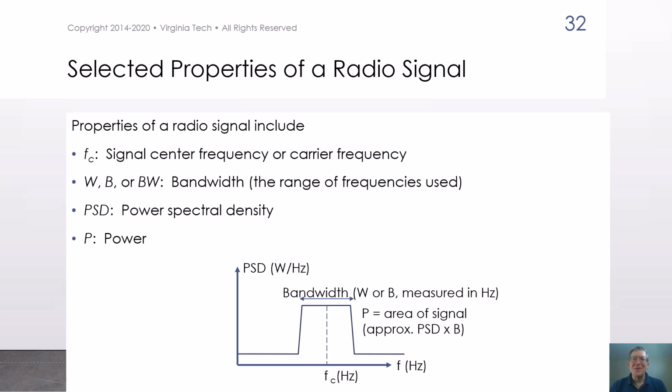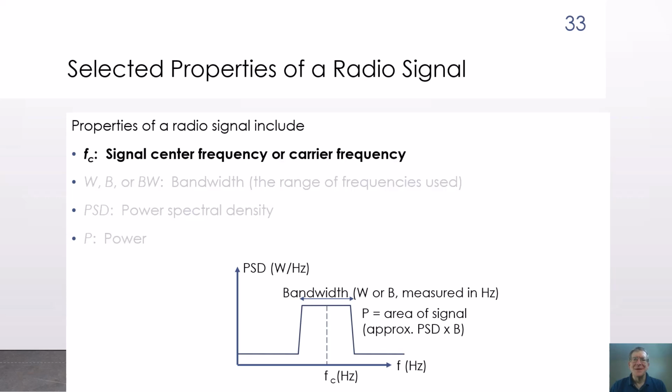Radio signals carry information over a channel. A radio signal has several properties that will be of interest for this course as well as in other courses in the series. Anyone who has used an AM or FM broadcast receiver has encountered the first property, frequency. This is the number of oscillations or changes in polarity of an electromagnetic wave during a unit of time. These changes occur in cycles. For example, the electric field at a particular location changes from one polarity to the opposite polarity and then back to the original at regular intervals over time.